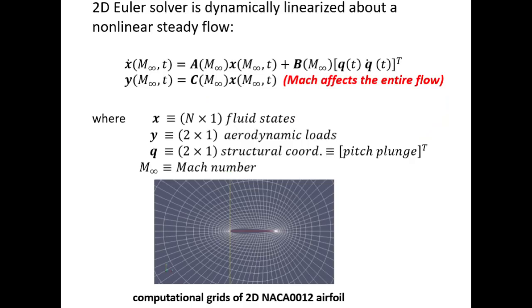For an application of the higher order MEPs, consider the 2D airfoil undergoing plunging and pitching motions in the subsonic flow. We used an Euler CFD solver to model and simulate unsteady oscillations of the wing in the compressible flow. The picture shows the computational grids used in the modeling.